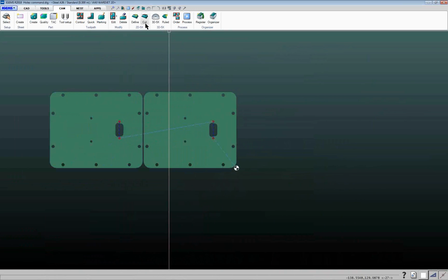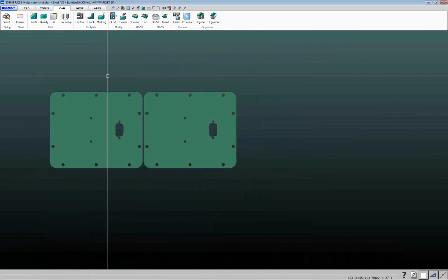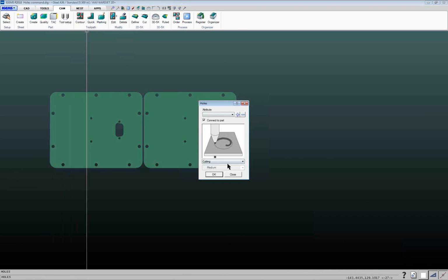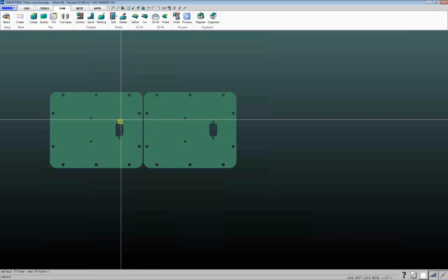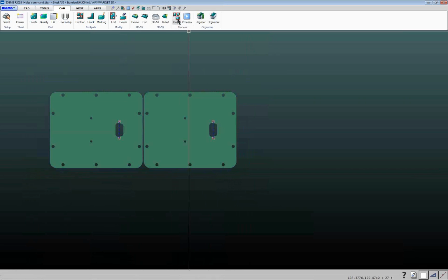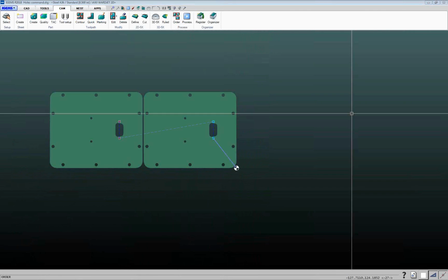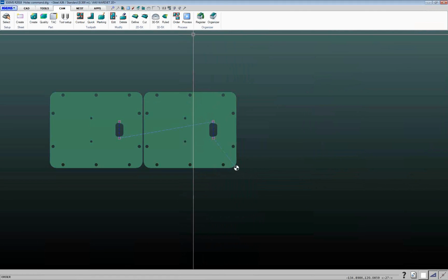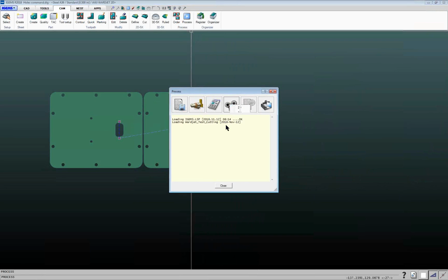And we'll go ahead and delete those. And I think that was all I wanted to show you in there. There's a subroutine thing that they added for one customer in particular, but the big ones in there would be the drilling, the marking, and the cutting options. Stationary would be similar to the marking one in that it would just do a stationary pierce at that location. So if you wanted to actually pierce through versus just making a light mark, if you use the stationary option, it'll use whatever number is in the material file for the delay at that point.